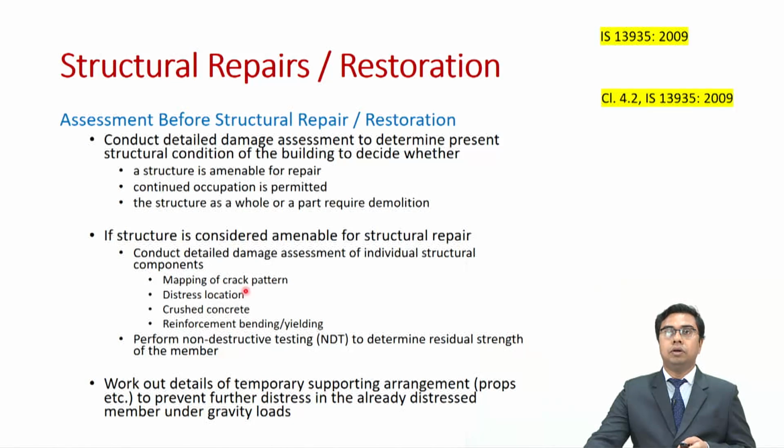we will do the mapping of crack patterns, we will identify the distress locations, we will also look at the crushed concrete and reinforcement bending or yielding. So, all these distress signs we will record. We will also perform some non-destructive testing to determine the residual strength of the member. We also have some non-destructive testing related to masonry walls as well. For that, you need to look into relevant literature.